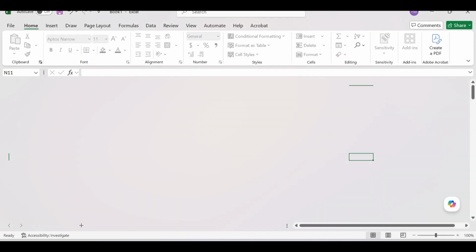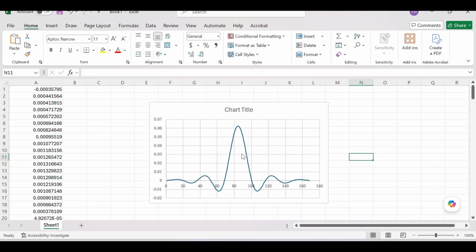I exported them to a file, and then I brought them to my Excel, and I plotted the coefficients, how they look like, just to make sure that the structure I have for these coefficients is symmetric. And this characteristic of being symmetric is important for me. It's a good thing, because it makes you reduce the number of multiplications by half, just because it's symmetric. So it's a very efficient way of processing the computation for the FIR.